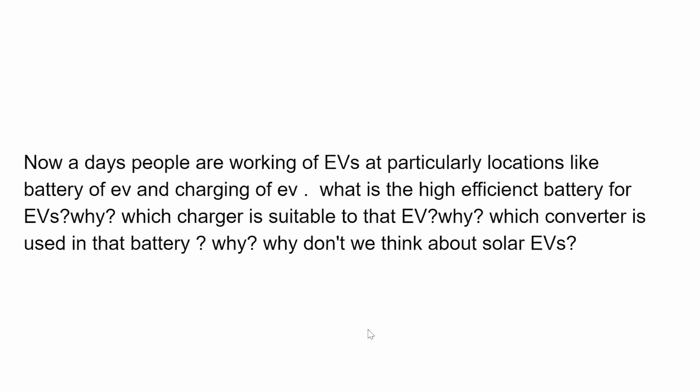Solar electric vehicles, solar will never be able to charge the EVs at the rate at which the electricity is being consumed. So you can have that as an additional feature, but it will never be sufficient. You can't just always use solar. If you are going on a 300, 400 kilometer long drive and you're driving continuously, the solar will never be able to charge it in such a way that you sustain that drive. You need to park it for a long period of time so that you get some solar charging. And which charger is suitable?